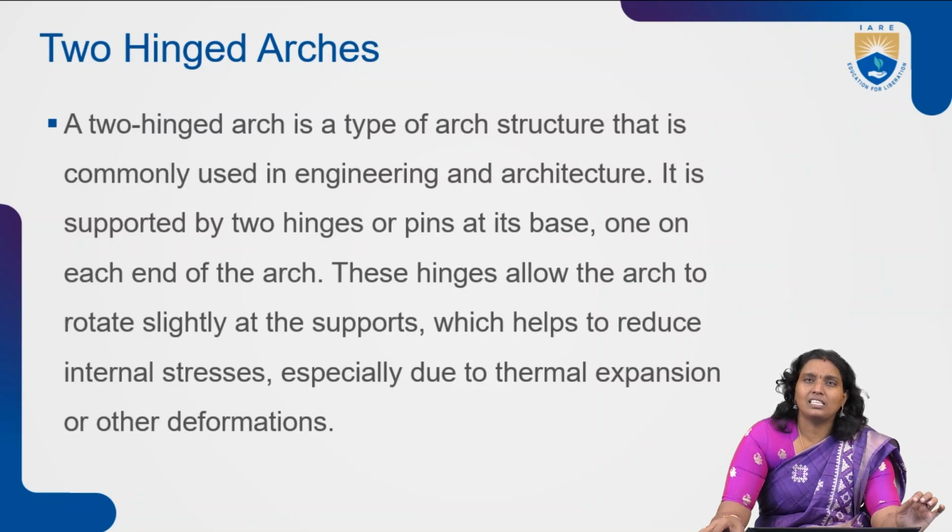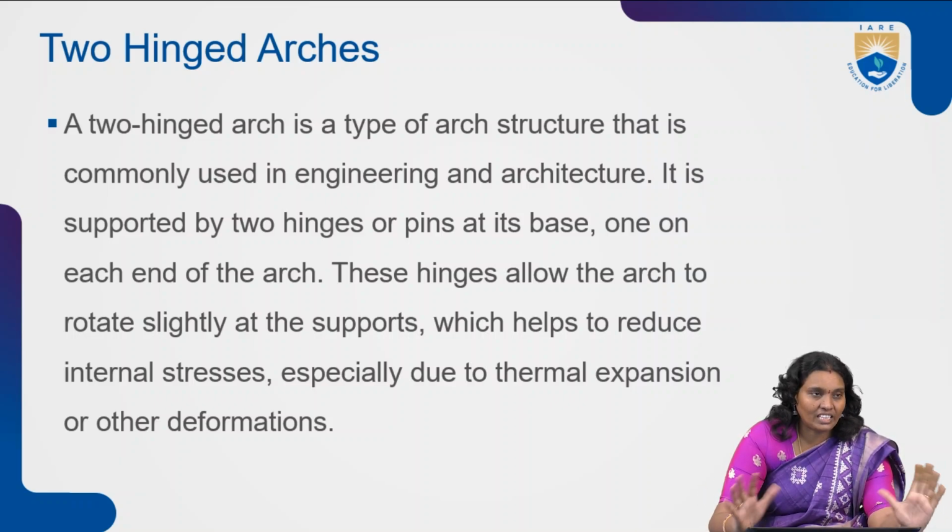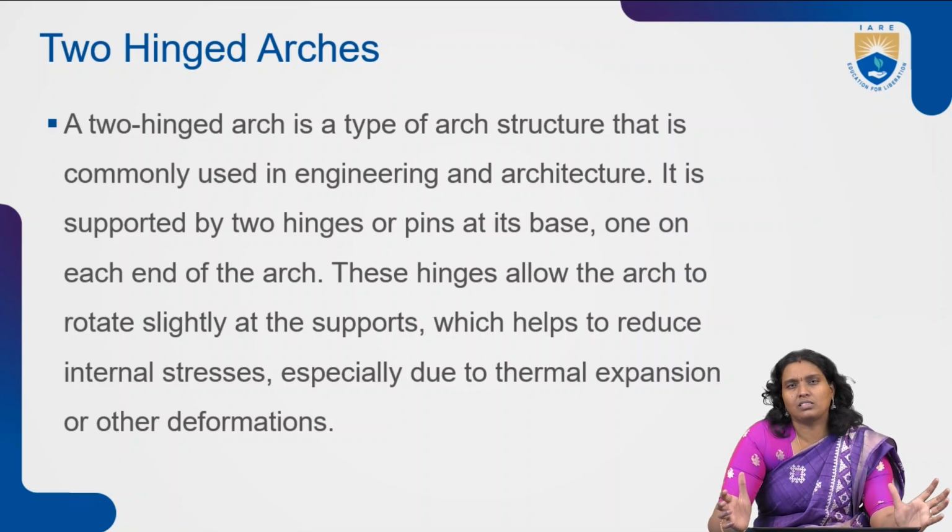This is a structure used in engineering as well as architecture. As civil engineers, we use these types of arches to reduce the internal stresses, and also, due to thermal expansions and other deformations, we have to provide support for the structures. In those situations, we choose these types of two hinged arches.